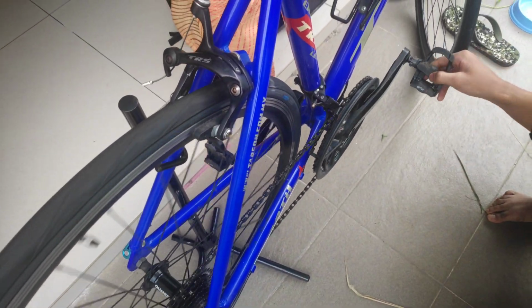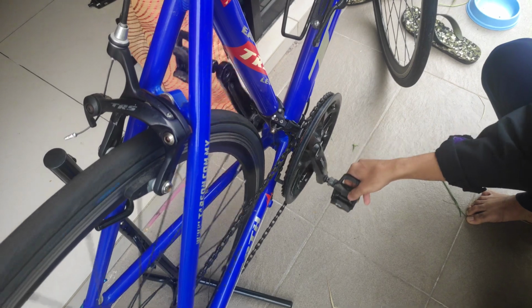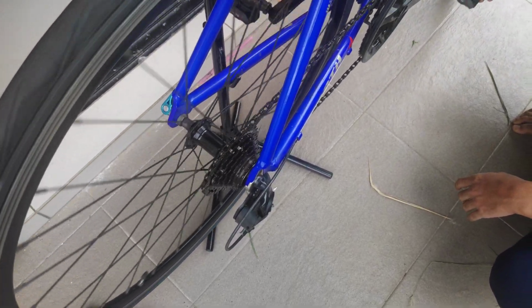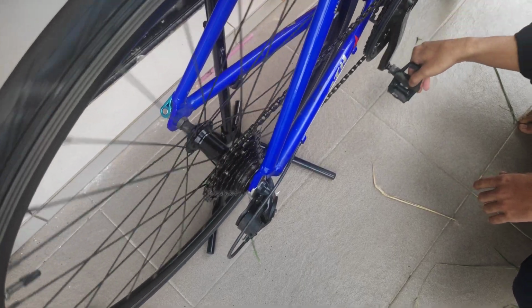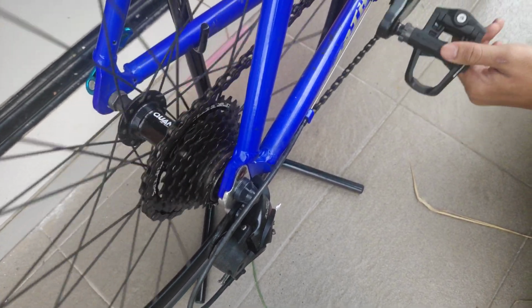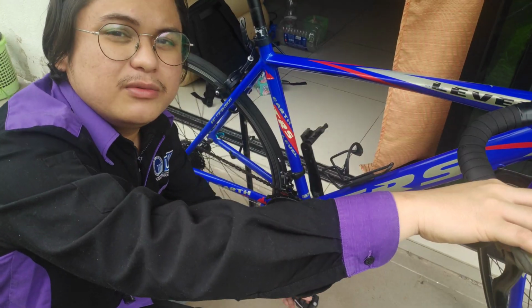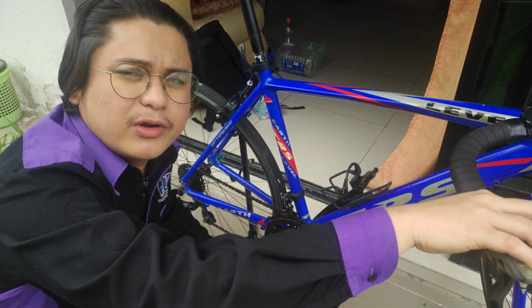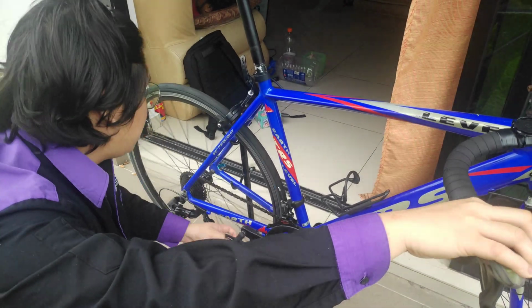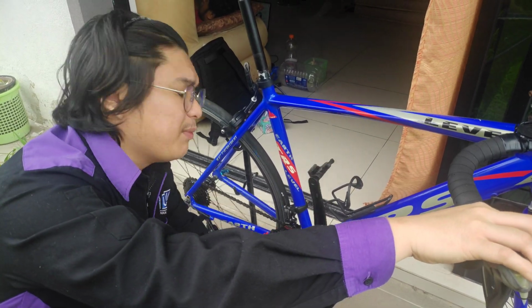So for this lab test, the driver gear is going to be fixed at 53 teeth, and we're going to change the driven output from 26 teeth to 14 teeth. So 26 teeth is the lowest speed, and the highest speed is for the smaller gear, which is the 14 teeth. Okay, now we're going to change from low speed to high speed, which is from the large gear at the driven to the smallest gear.